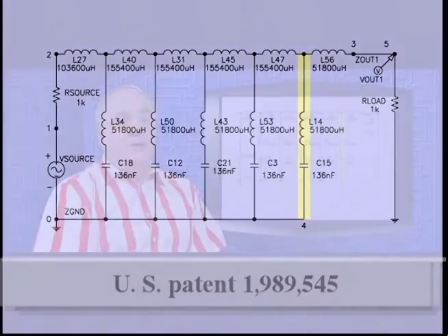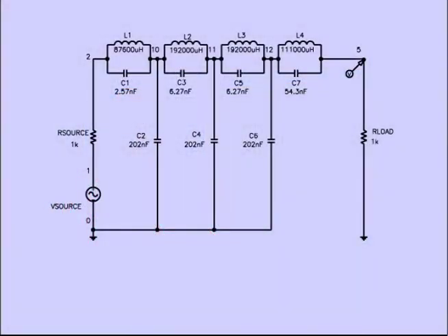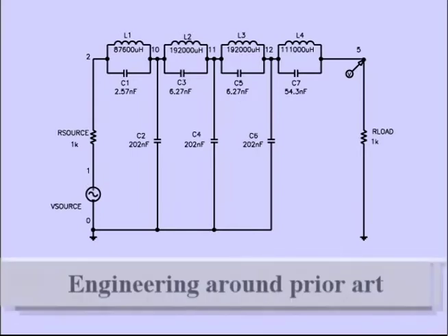In addition, genetic programming can be actively directed towards novelty. For example, the elliptic filter topology was separately rediscovered on a run of genetic programming using a fitness measure designed to explicitly engineer around the Campbell patent. A graph isomorphism algorithm was used to explicitly reward circuits that differed topologically from the Campbell topology.